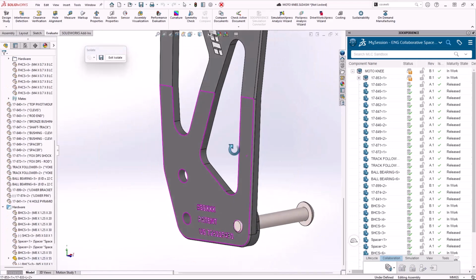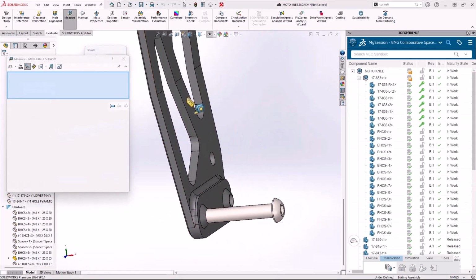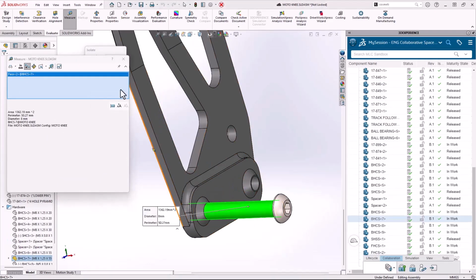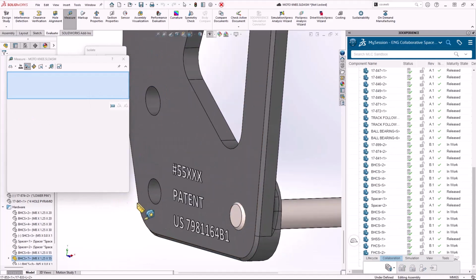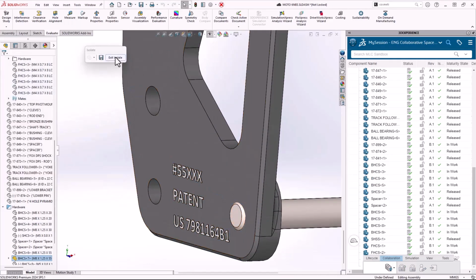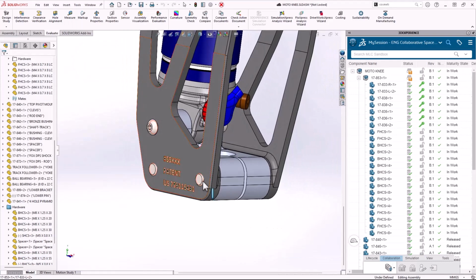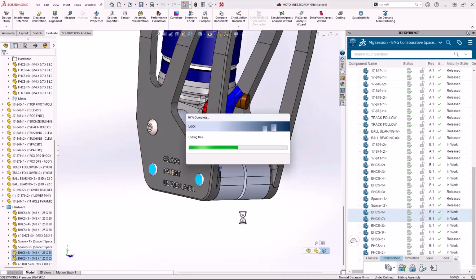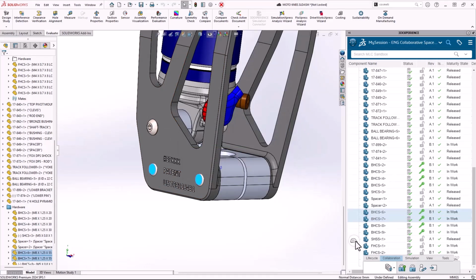To start out, I'm going to use my measure tool to verify the diameter of the hole, which is 7 millimeters, and then also the diameter of this hardware, which is 8 millimeters. That explains partially why we're getting some geometry overlap in that area. So as opposed to changing the hardware, which is usually standardized, I'm going to adjust the holes on the plate.